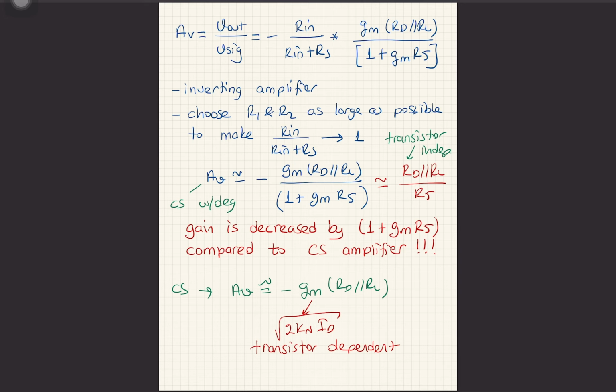So it's like one advantage and disadvantage. Disadvantage, you sacrifice from the gain, but the advantage is you make a circuit where the gain only depends on RD and RS value. It is not transistor dependent. If something happens to your transistor, when you change it, you will still have the same gain. So in terms of that, you have a more stable operation.